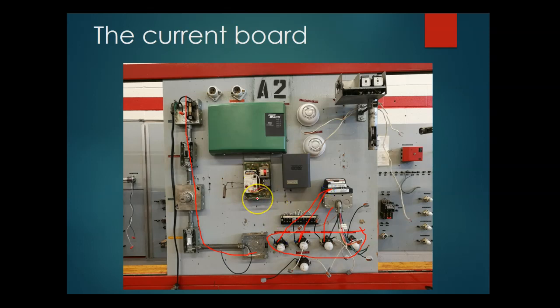And this is my aquastat, and this is the switching relay here. And we have two thermostats, thermostat 1, thermostat 2. One of them will connect to the thermostat over here, and one of them will connect to the thermostat over here. And this B1 will connect to the primary.